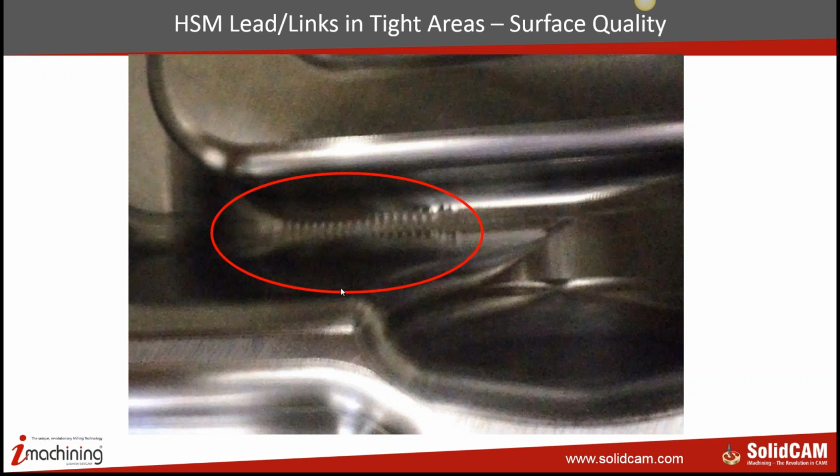It's almost 11.5 millimeters in width, and we were using, I think, about a 10 millimeter cutter. So whenever the cutter left one wall and went to the other wall, the tool was always deflected. Whenever the tool left the wall, it used to come back to its original state. Even a small deflection, like 50 microns, is good enough for it to start creating marks on the bottom.